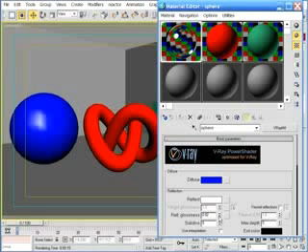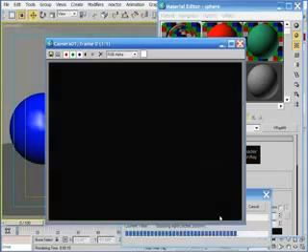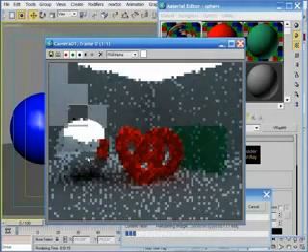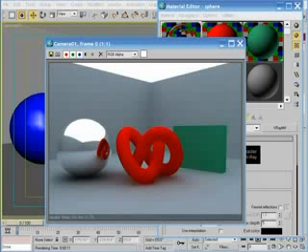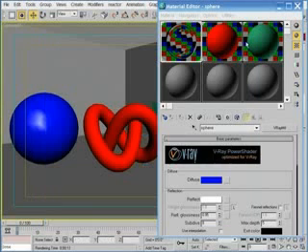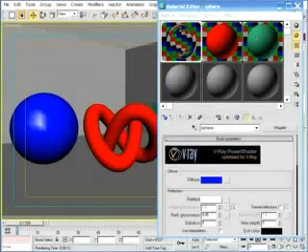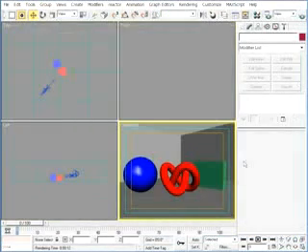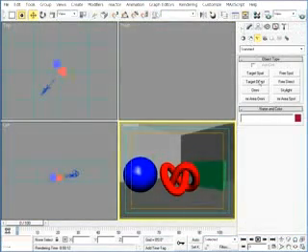And the reason the highlight becomes larger is the light is being scattered over a greater range of angles. So let's see this in action. If I change the reflection glossiness to 0.95 in render, I will actually see no highlight. Any idea why? Well, it's because the only source of illumination in the scene is environment light. So there's no actual light source to reflect.